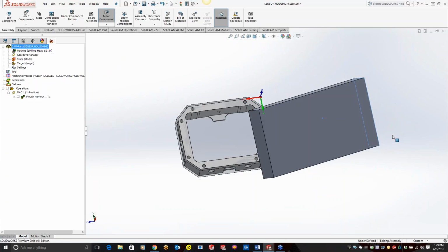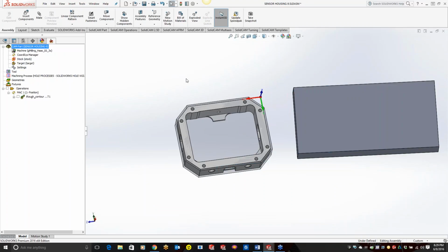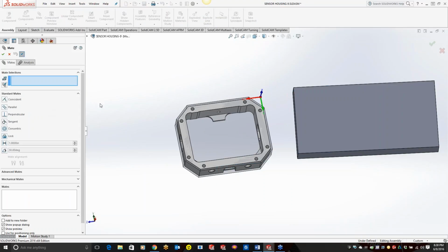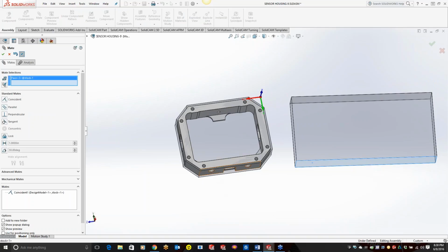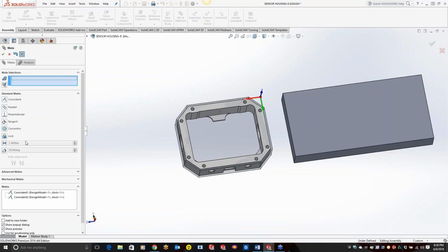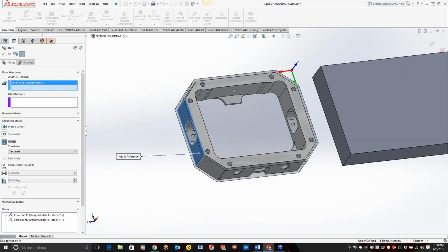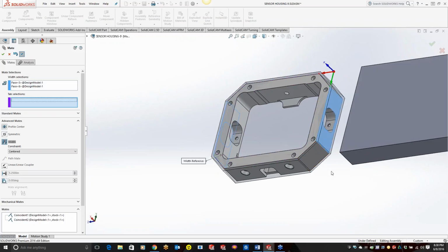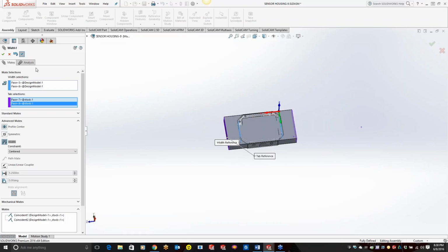Now you can just click wherever you want. You can orient it, you can move this around. Right now it is a free floating stock. So what you'll have to do is use your SolidWorks and come in here and mate everything up. Go right here, and maybe we'll just do a width mate. For those of you who don't use a width mate, that is a nice feature that SolidWorks has. Just click on the width and it centers everything up for you.